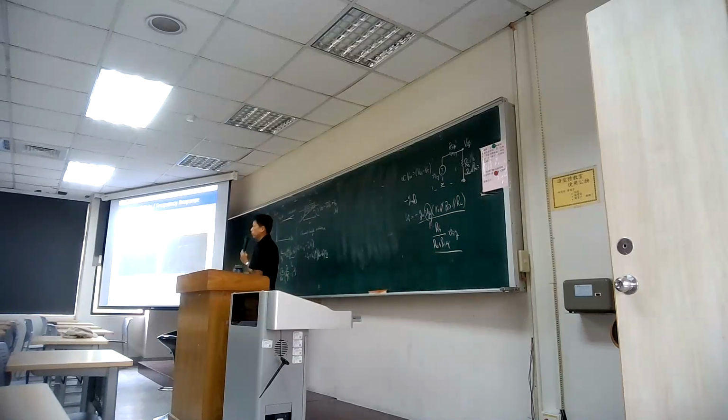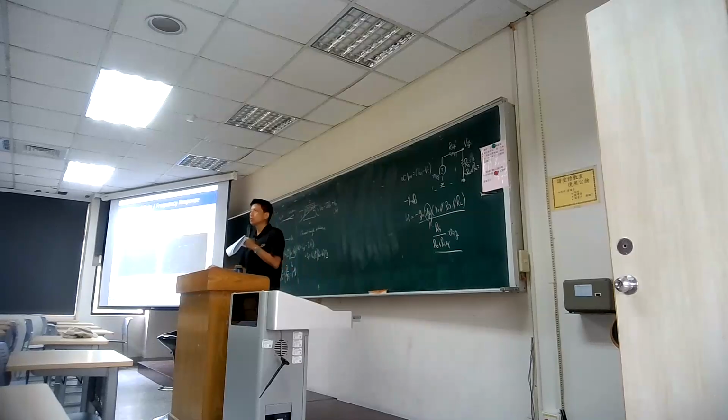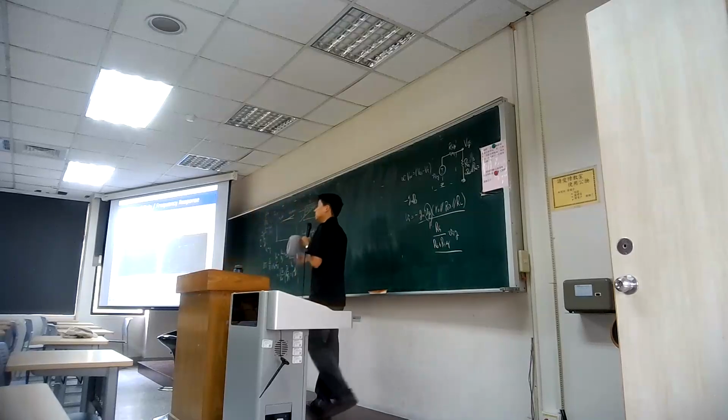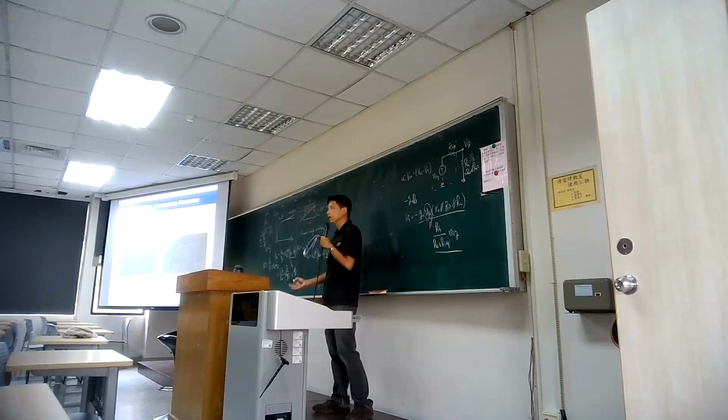So we want to have the CPU get better performance at a high frequency. So the question is why we have this high frequency response and how do we improve it? You can see if there is a capacitor, we need to charge up, and then we need to deplete the charge in order to turn off your transistor. And during this period, the delay times will be proportional to RC.